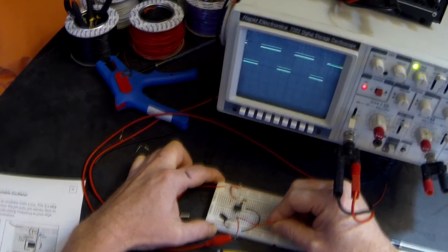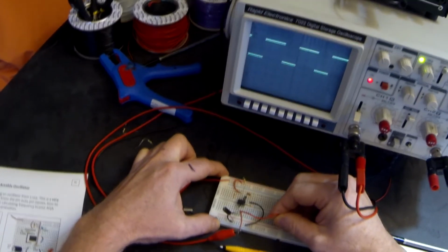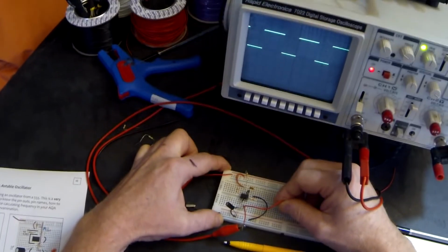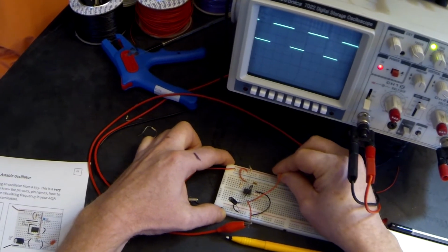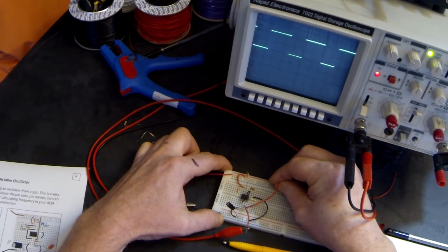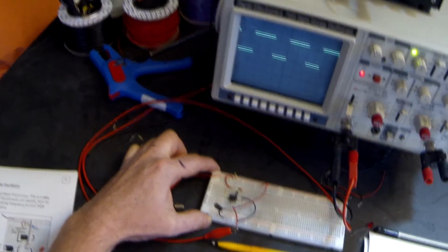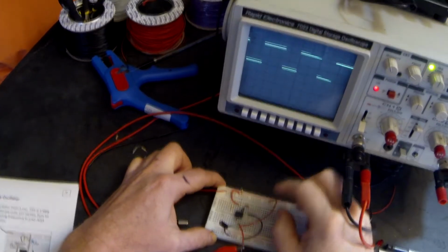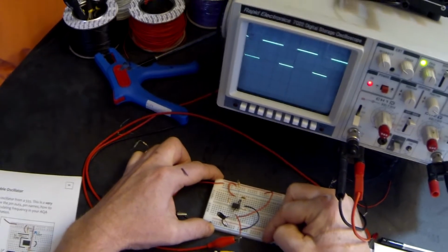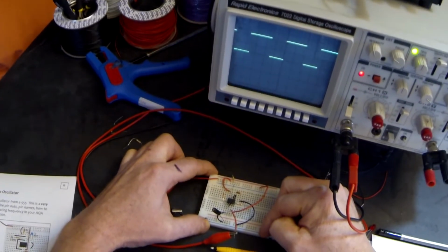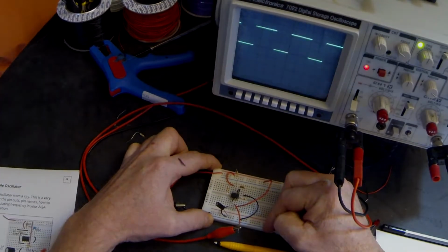In other words, it's not connected to 0, and it just recognizes that the wire is not connected to 0, so it doesn't matter about being connected high. But it is always worth putting pin 4 high so that it is not recognized as a low. But when it goes low, it is reset and the output of the 555 stops oscillating.